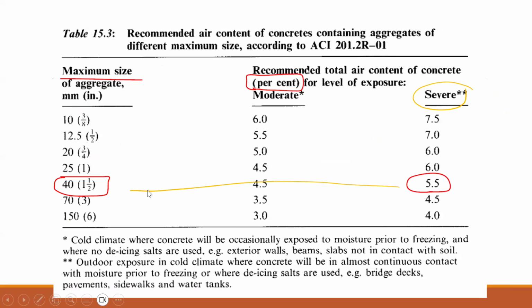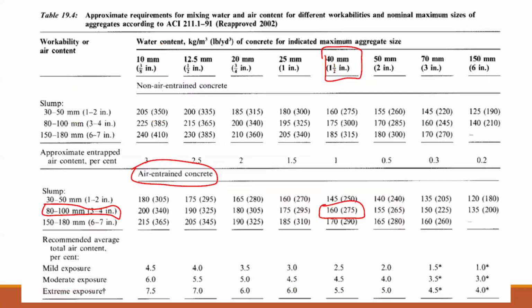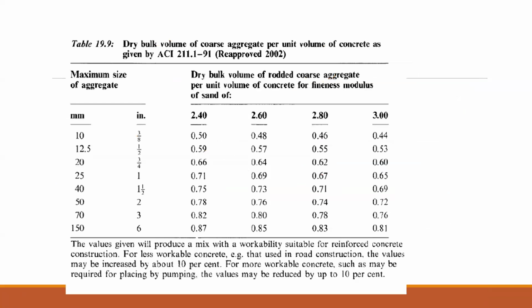Concrete, when it reacts with sulfate, it expands. So when it is expanding, we should provide that space to expand, otherwise the concrete will crack. That's why we are purposely adding air. When we purposely add air, we call that air entrainment. That's our air entrained concrete. Okay, so we did this, right? Yes.